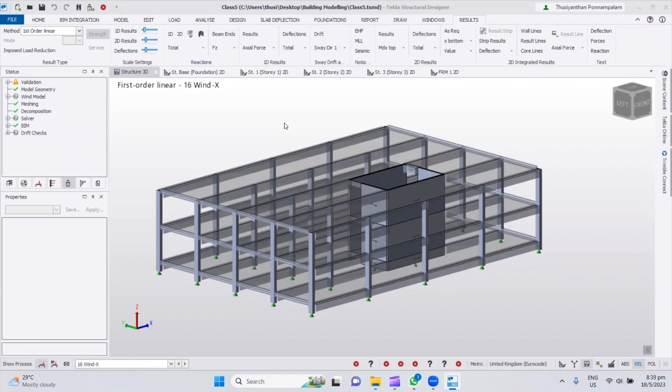I presume you already know the theory, how to do the flat slab design manually, or we use the 2D frame analysis method, right? When you consider flat slab, the traditional way is the 2D equivalent frame analysis. Some common wording is column strip and middle strip, right?